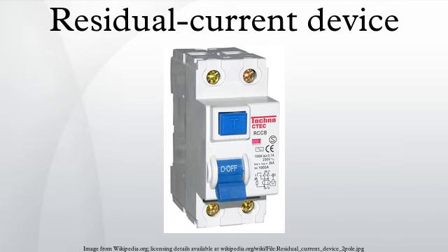Overcurrent protection must be provided. Circuit breakers that combine the functions of an RCD with overcurrent protection respond to both types of fault. These are known as RCBOs, and are available in 2, 3 and 4-pole configurations. RCBOs will typically have separate circuits for detecting current imbalance and for overload current but will have a common interrupting mechanism.